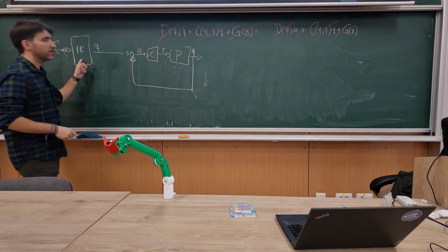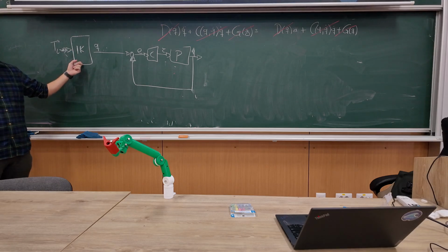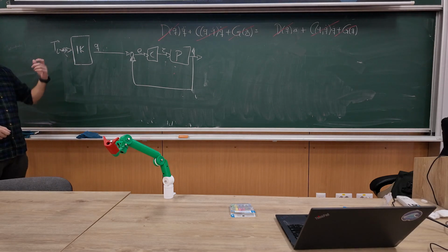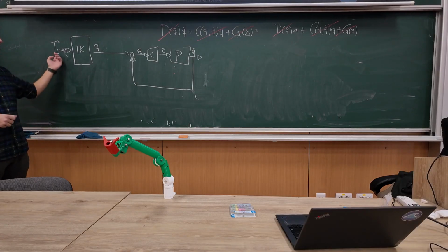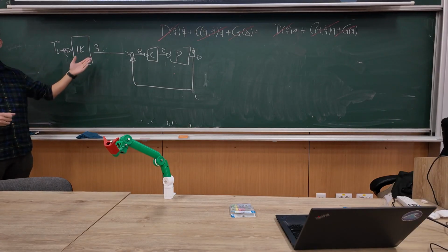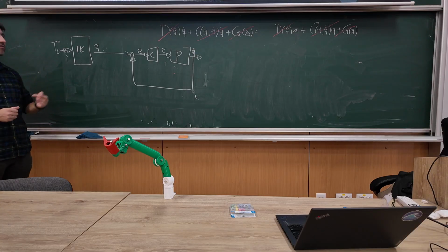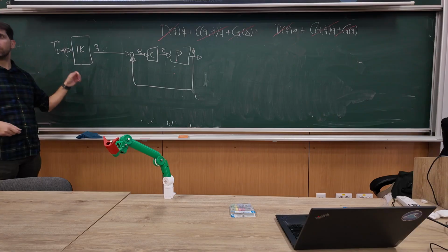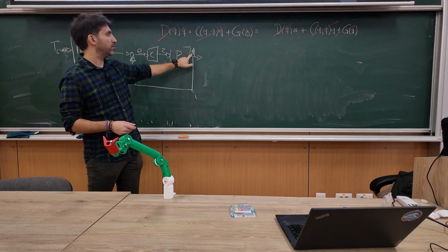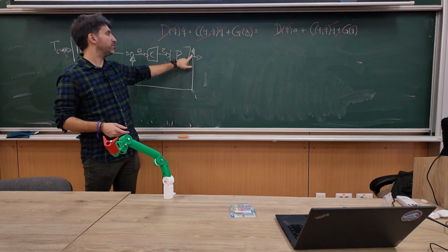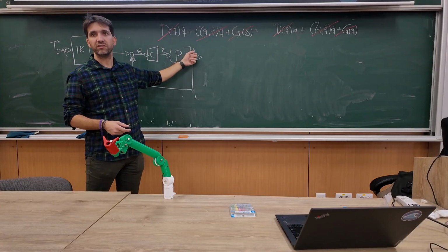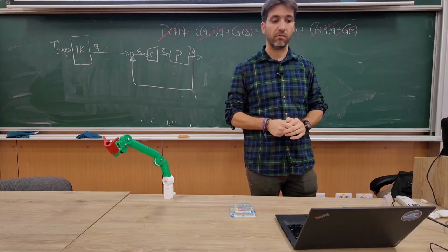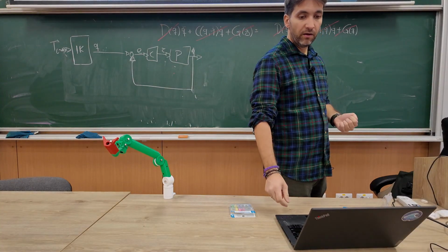Because this thing we can know with good accuracy. We can model the forward kinematics good enough so that we know the inverse kinematics good enough, then we can do this open loop. We don't have to really verify. We can verify as well, but in order to verify, we'll need an extra sensor. It doesn't make sense to do it through this one, because if there is a problem, it will be something with the way the joints are reported, or something along those lines. All right.